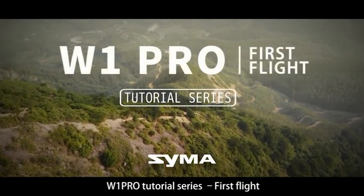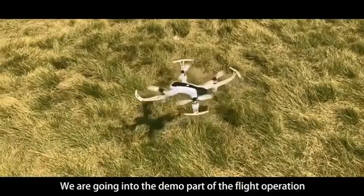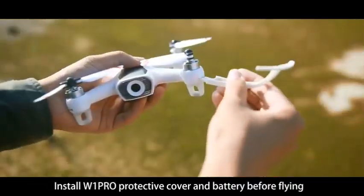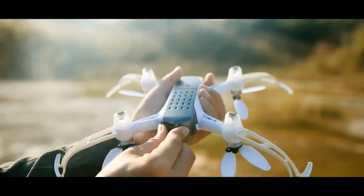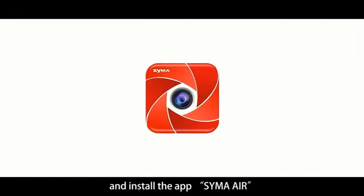W1 Pro Tutorial Series: First Flight. We are going to the demo part of the flight operation. Install the W1 Pro protective cover and battery before flying. Mount and fasten the phone to the stand. Scan the QR code to download and install the app Syma Air.